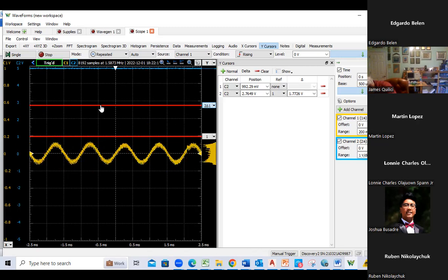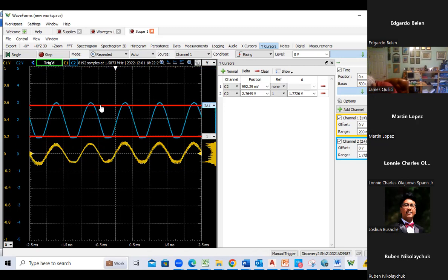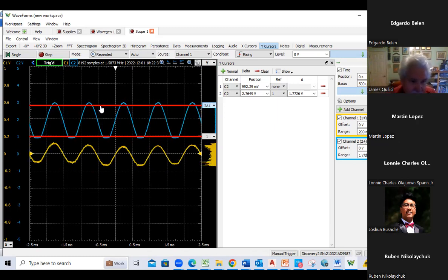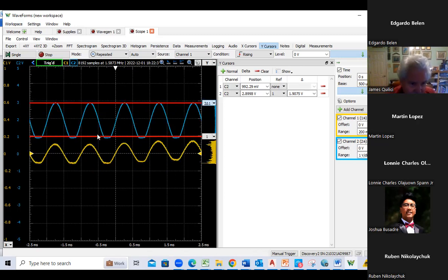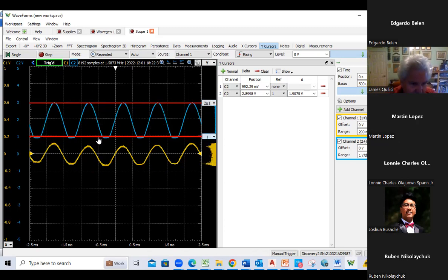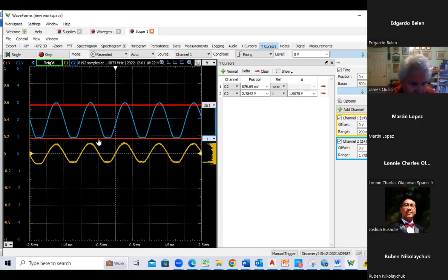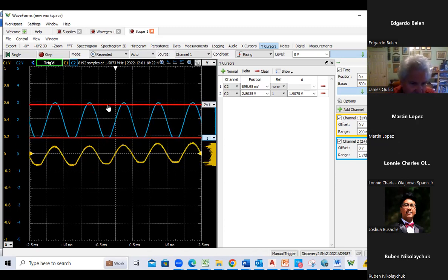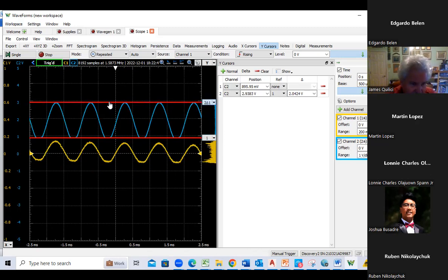I think my spec is I needed 2 volts peak to peak. Yeah, I'm running into my negative supply. So this isn't optimum. But I think I've at least got my gain. I would have to tweak around with it some more to see if I can raise the collector voltage up.